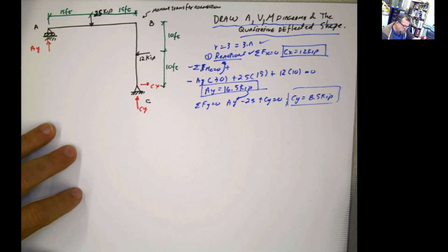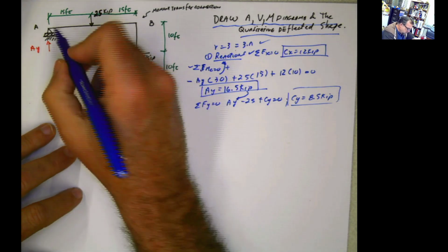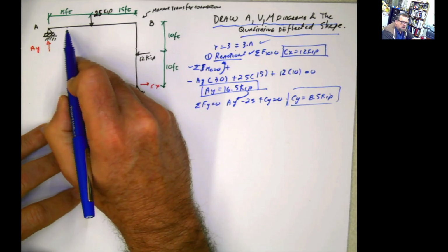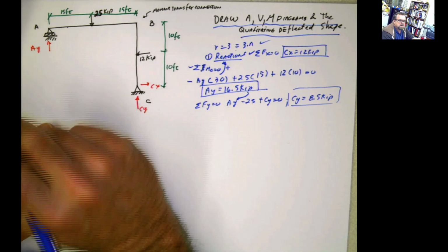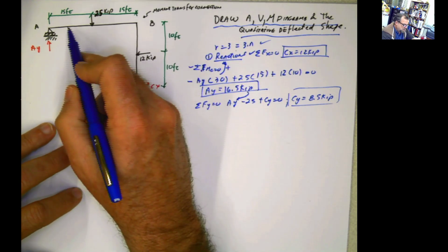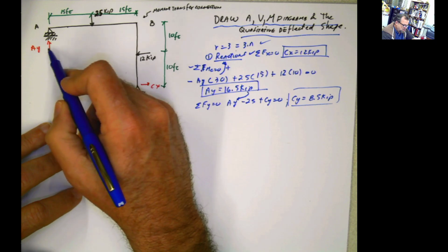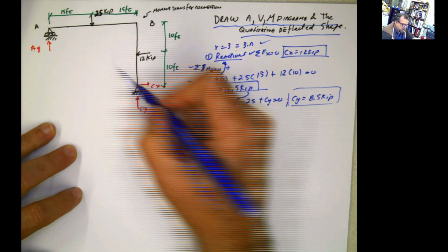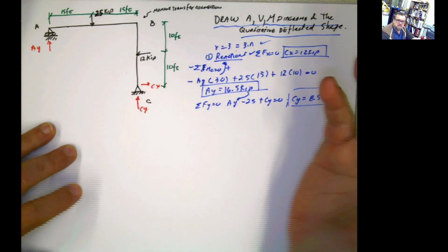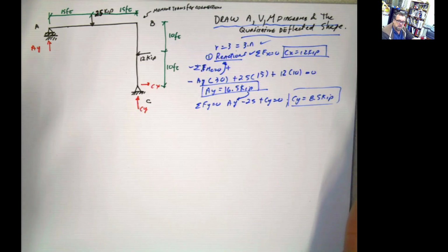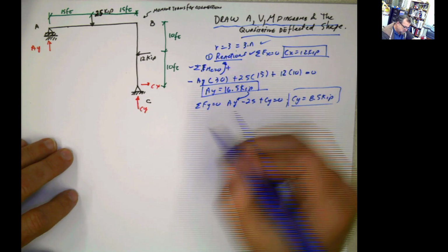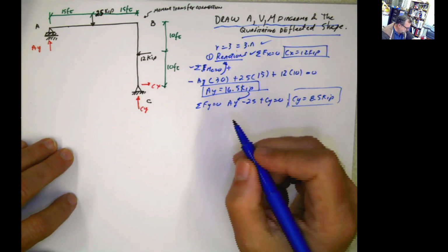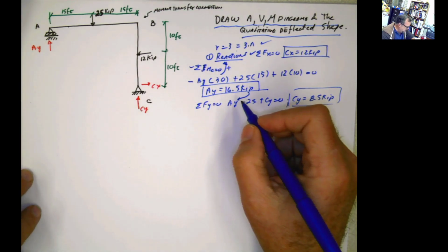Now try not to eliminate any force. For example, I can do moment with respect to a point. And what is that point? You decide. You say, okay, this is 1 feet, and then you do moment with respect to that point. You put the values of AY and the two other reactions, keep all the forces, and at the end the summation of moments has to be equal to 0. That's it, nothing else. But verify the reactions. This is an important step, and a lot of people don't do it.